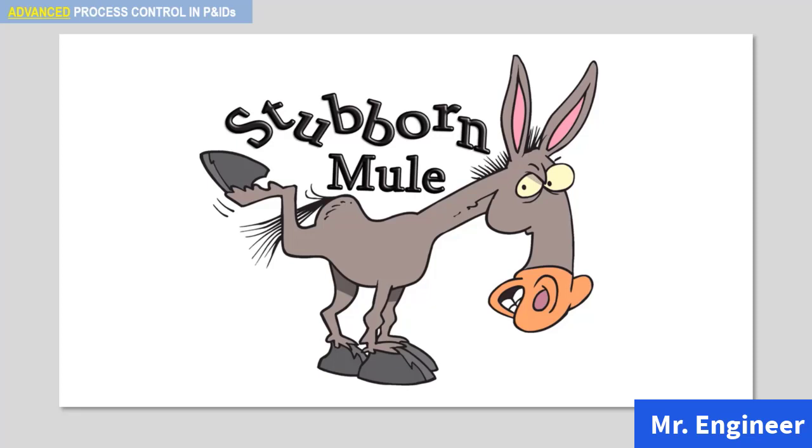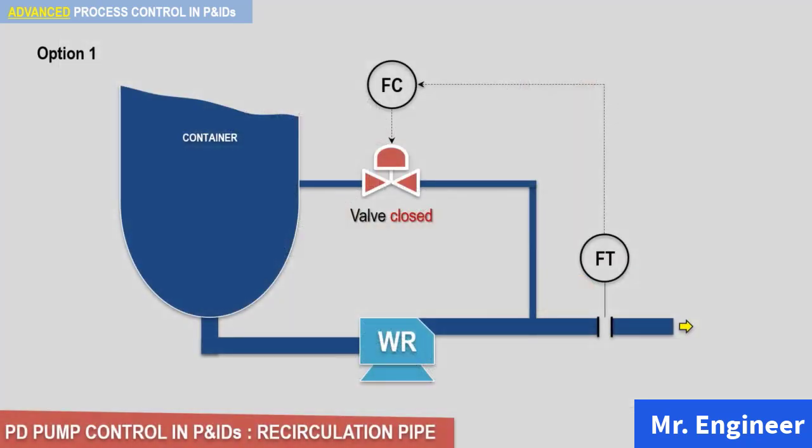The first arrangement is shown in this P&ID schematic. This arrangement shows how we can control the capacity of the positive displacement pump by using a recirculation line. The flow sensor is located on the discharge line outside of the recirculation loop. If the rating of the pump is 10 cubic meters per hour and the equipment downstream is only drawing 8 cubic meters per hour, this means we need to recirculate 2 cubic meters per hour.